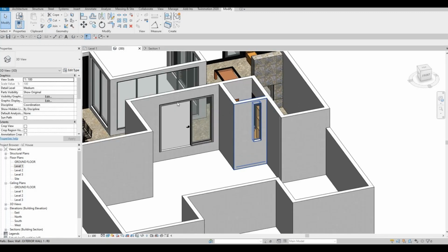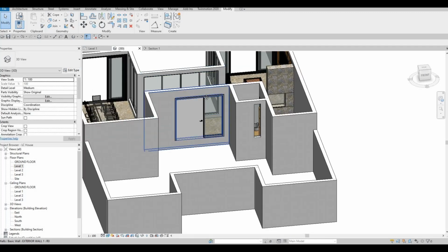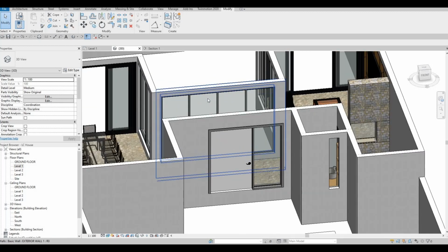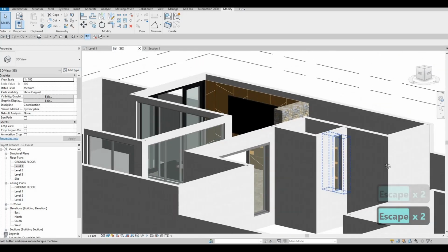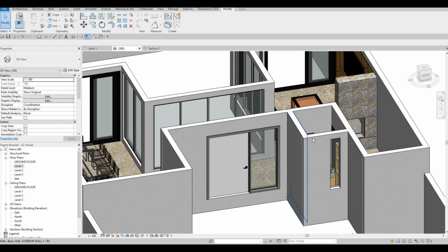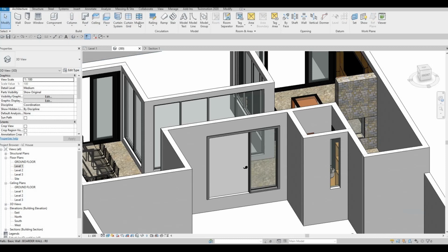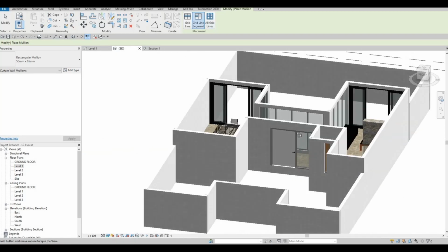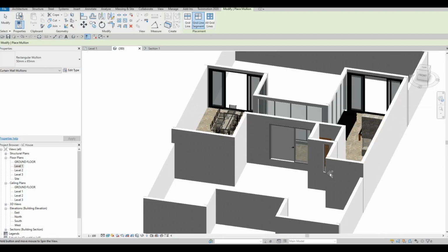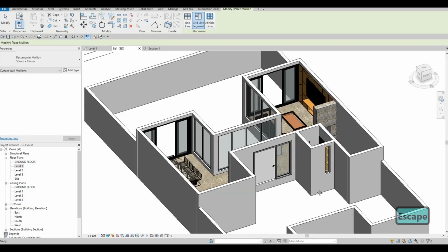And I always like to have everything consistent with height. So here, I'm going to align it from the top here and then align it right there. So that's perfect, same height, and then we have the width right there. So at least it's all the way at the top as well. And then now we just need to add a mullion and then all grid and then make sure this is 50 by 65. So let's click that, and that looks really nice, and that's good enough for that space.